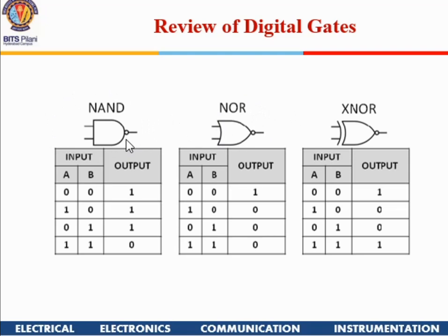Because physically you cannot make transistors, you can't arrange transistors in such a manner that the output will be AND. Once we read about these implementations in our theory class, you will understand that. So just understand that to make an AND gate, you have to make a NAND and an inverter at the transistor level.